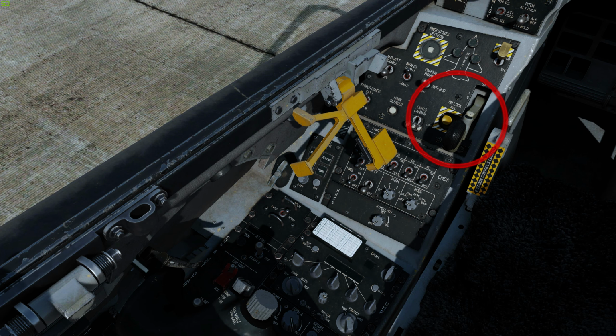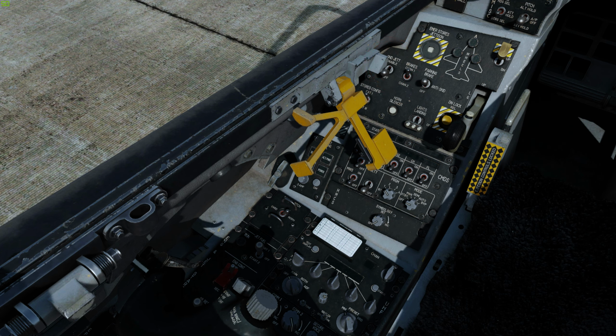The landing gear handle is in the down position. Ground jettison enable is off. This switch is used to enable jettisoning of stores while on the ground. The emergency stores jettison cover is intact. When pressed for more than 1 second, all air-to-ground stores and external fuel tanks are jettisoned.